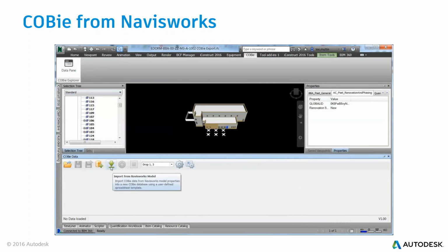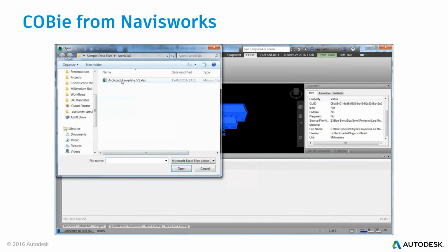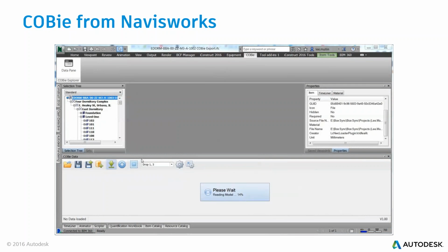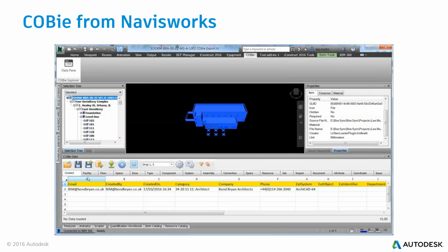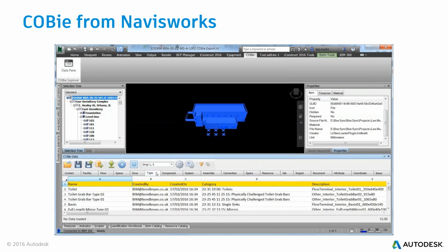So we're going to show a video, and again you'll have access to this, and this is with an IFC file from Graphisoft, from ArchiCAD. This is actually, for those who are aware, there's recently some test files that were provided by Bill East, who's a creator of COBie, and Bon Bryan Architects, which have got all the relevant COBie information. And this would allow you, using an ArchiCAD template, to be able to map all of those fields to the relevant COBie fields and then create your COBie spreadsheet.